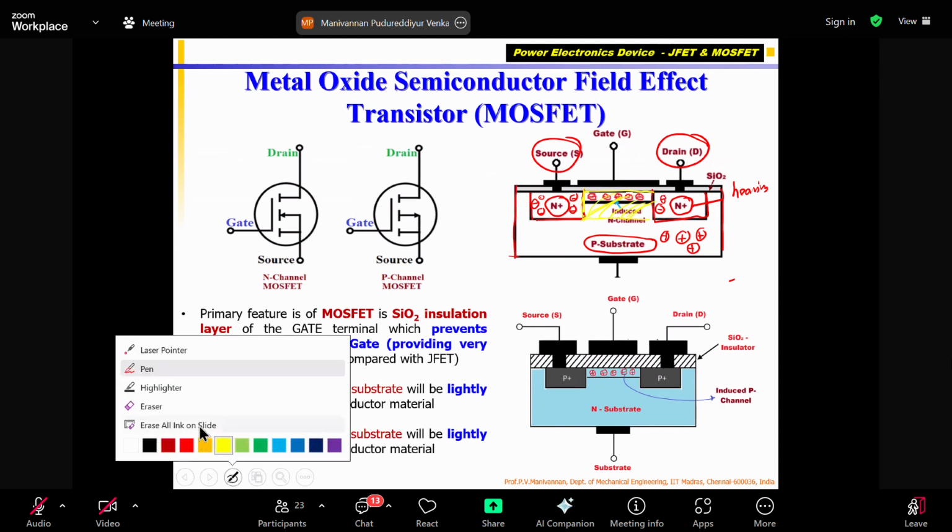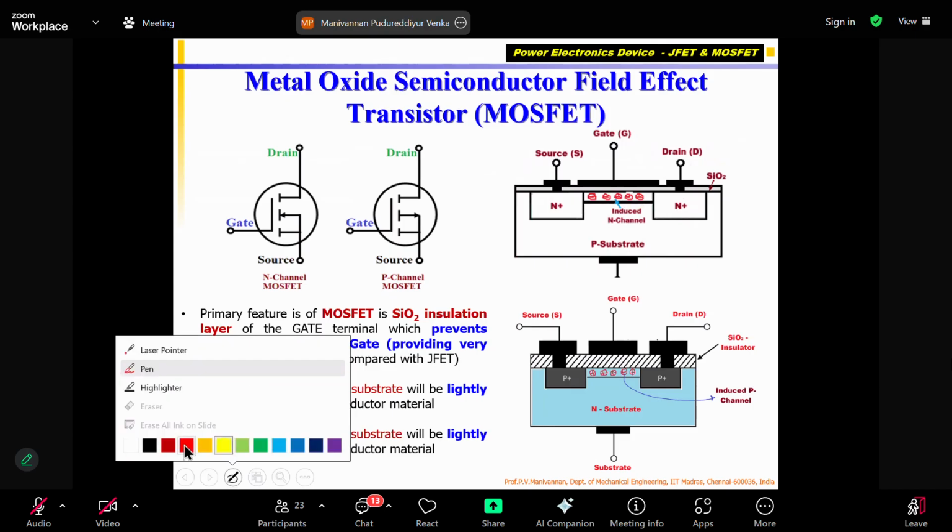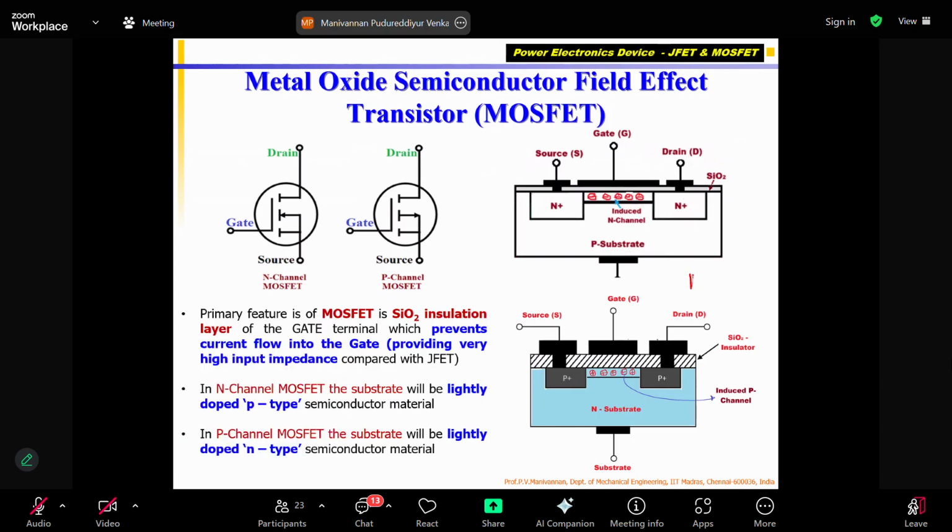Okay. P material, one more thing you have to remember. In semiconductors, they call 2 things. One is called majority carrier. The other one is called minority carrier. If I take P-type material, majority carriers are plus, that is holes. If you add 100 aluminum atoms inside the silicon of 1,000, replacing those, 100 holes will be there.